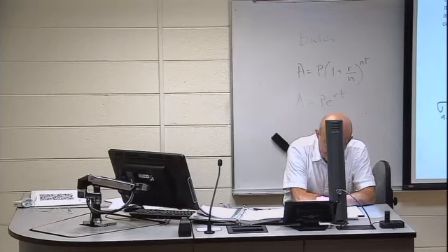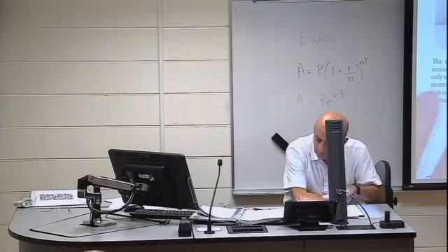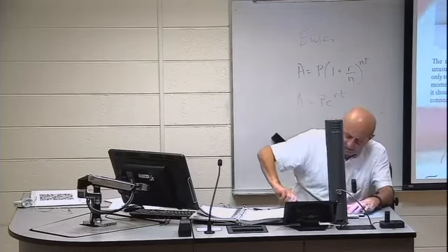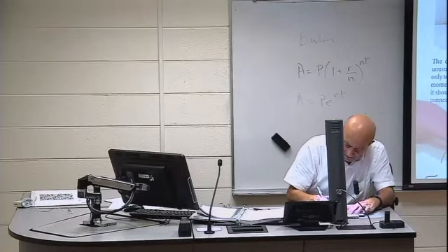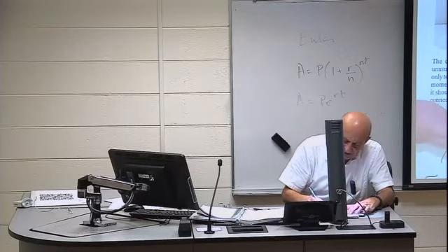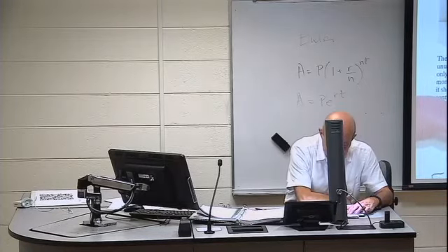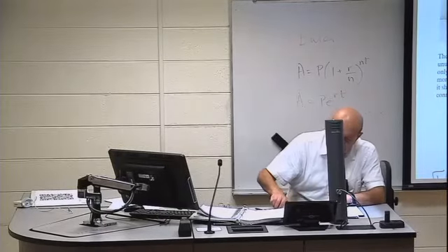Bending moment, we said before eccentricity, in the very first lecture on buckling, that Mz equals minus P times v. So that is ideal. Now there is this v and there is e. So bending moment equals minus P times (e plus v). This is known.